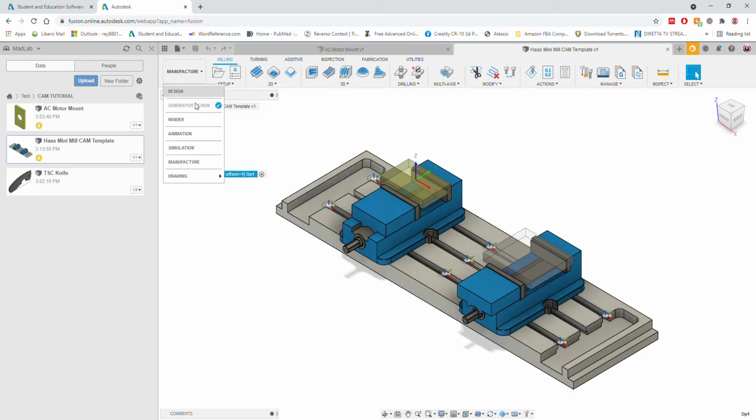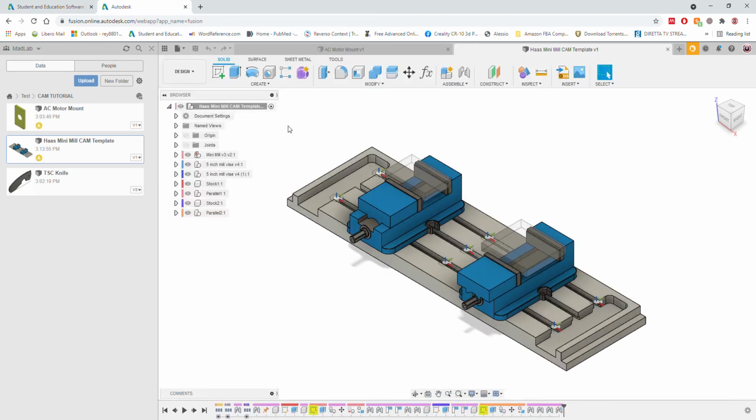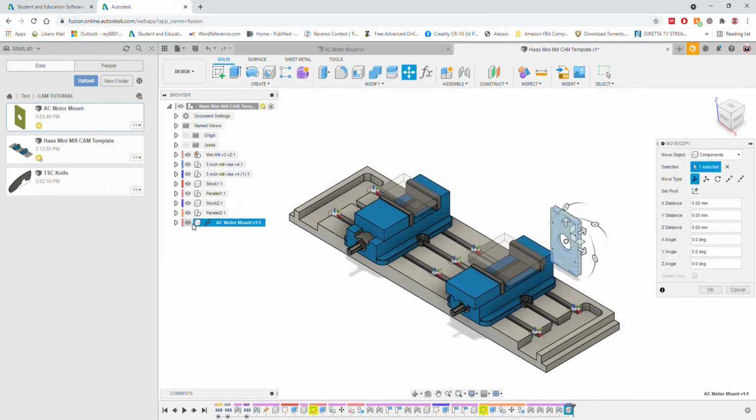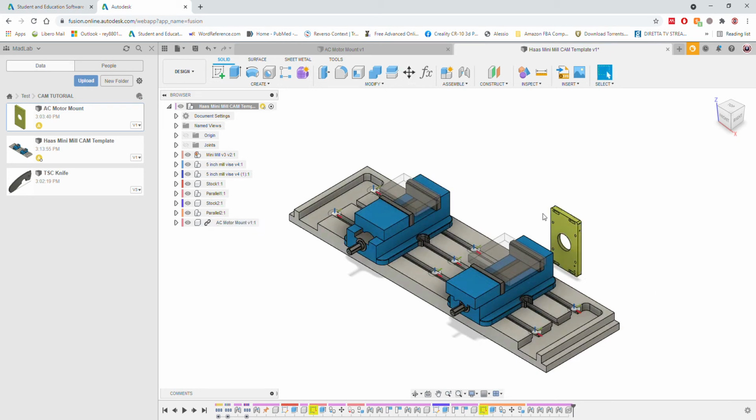So we go in the template design, because first we have to import our parts. We take the parts, you can drop it, you can drag it inside, or insert into current design. As you can see, it will be inserted as a separate component with a chain, so it's all linked, it's all bound. And now this one you don't care about, because it's just a temporary position in space. You can still move it all around, nothing is fixed in this case. Bring it back. But it's chained.